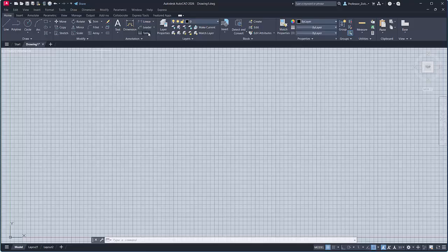And then we have annotations, which adds text and information to our drawing. And then we have the layers property. This is a very important menu. We'll be exploring it in some time because what it actually does is allow us to place our drawn items on very specific layers, or imagine, if you will, sheets of glass. And we can work on one sheet of glass at a time in this particular case, and therefore not affect any of the others. It's a management tool more than anything else. And then we have some other elements here and some matching properties and the line types and all that, but we'll get into that much later on.